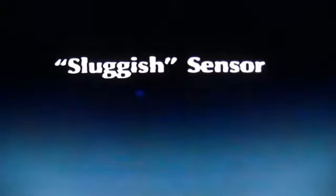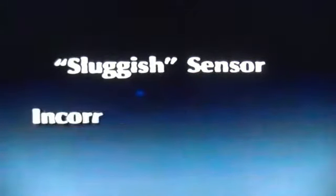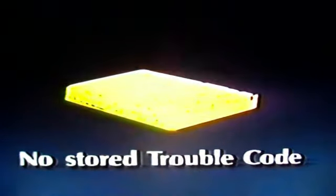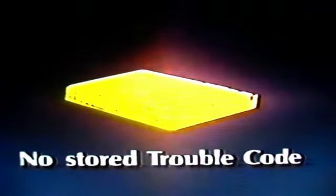These kinds of responses indicate that the O2 sensor is not working properly, and as a result, the air-fuel mix will not be correct. Incidentally, the car this sensor was taken from showed no stored trouble code to indicate an O2 sensor problem. That's because it was working within the narrow range allowable by the computer. Or in other words, it was working, but not effectively.